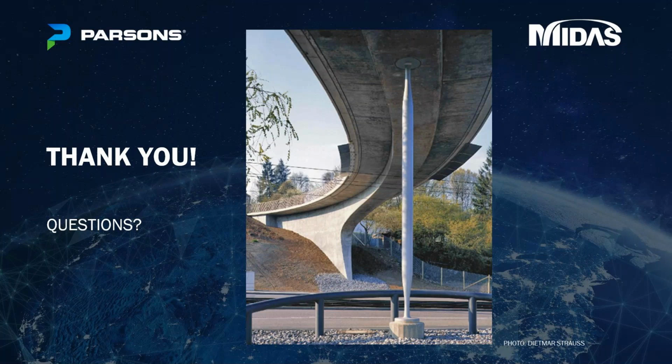And typically what you do is you have a p-y curve, so you have the force and you have the deformation of the soil accordingly. And then you need to iterate in your model to see that the deformation and the force that you get from your model match, so that you have the right performance.